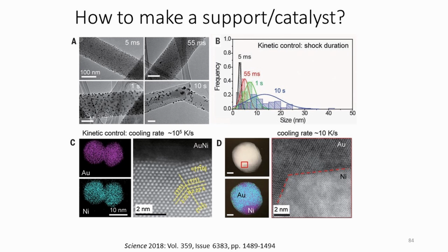This method is often considered to be more difficult and indeed requires accurate control of conditions and hence the use of more complicated equipment. All catalyst features, like the surface area of the active phase, porous structure, particle size and shape, etc., strongly depend on the process conditions, like the nature and method of dosing of ingredients, mixing and stirring.